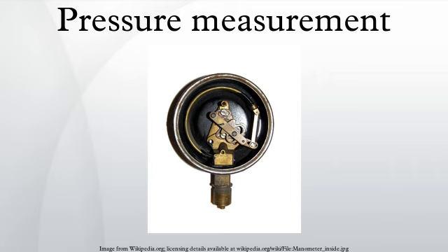The American Society of Mechanical Engineers has developed two separate and distinct standards on pressure measurement, B40.100 and PTC 19.2. B40.100 provides guidelines on pressure-indicated dial type and pressure digital indicating gauges, diaphragm seals, snubbers, and pressure limiter valves.